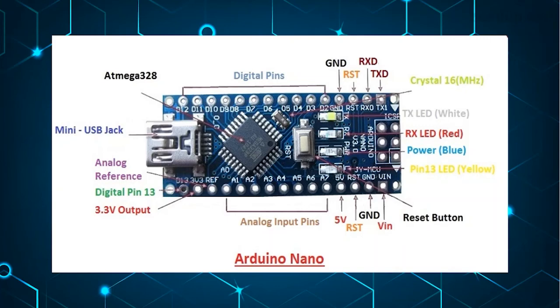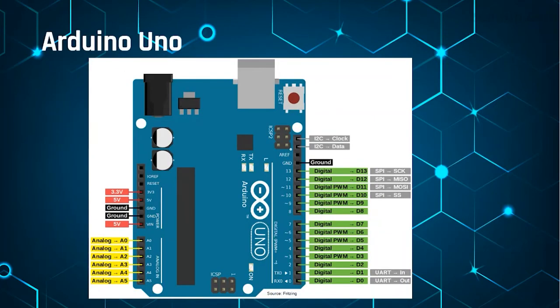Next comes the Arduino Uno board. The board size is greater than the Arduino Nano. The Uno has in total 3 power pins, of which one has a power supply voltage of 3.3 volt and the other pin provides 5 volt. All power pins have a maximum current of 50 milliamps or 50 milliampere. You can use the V-in pin to power the whole microcontroller with the same recommended voltage of 7 to 12 volt, also perfect for a battery.